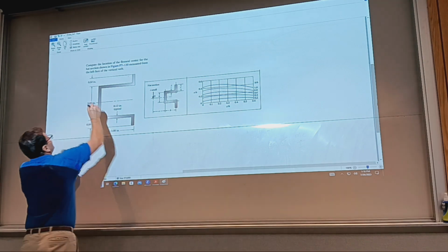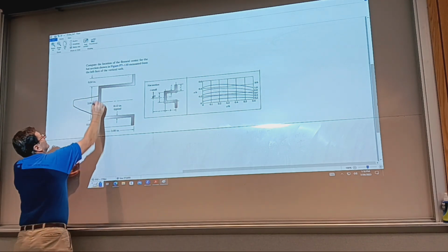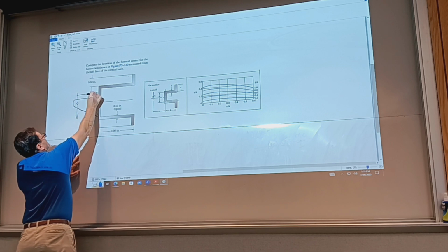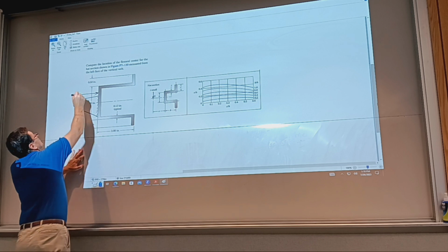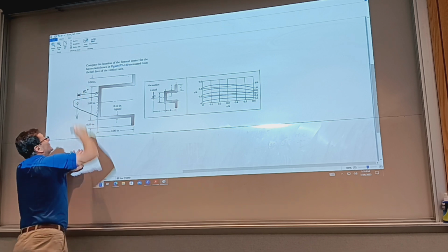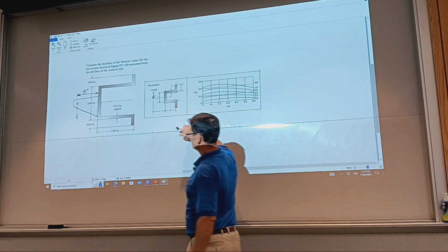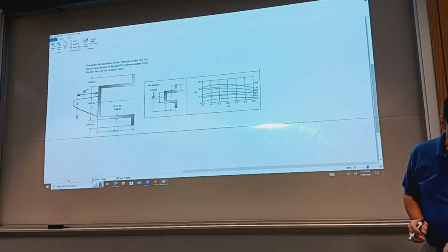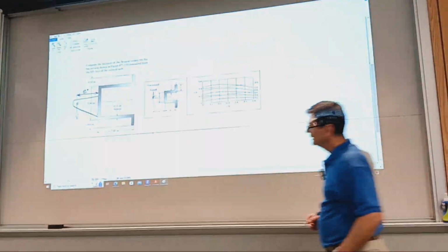So you'd have to fabricate a bracket and weld it here. And where does the force go? We need to report for this problem what this distance is. So it will be our E. I put a star. If you look at the entry for non-flexure center or shear center, this is page 424.